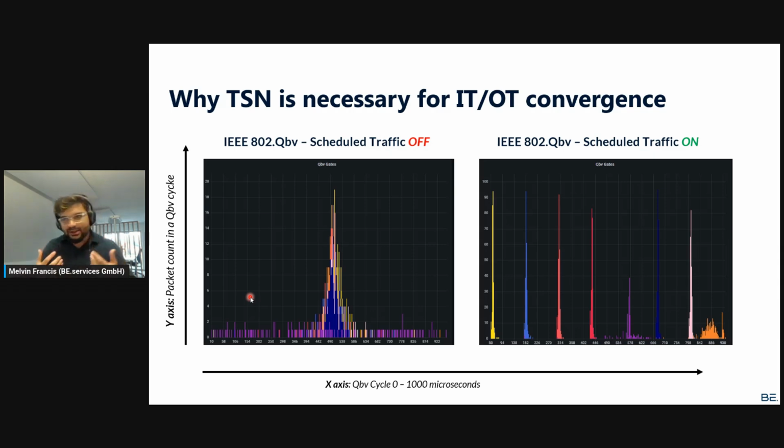I would say the best method is OPCUA, but still there is a problem if you don't have your network layer configured properly. So when you push your data from your factory floor to the cloud, you obviously would need an active internet connection, and there can be different types of traffic available on the network. So that's what you're seeing on the left.